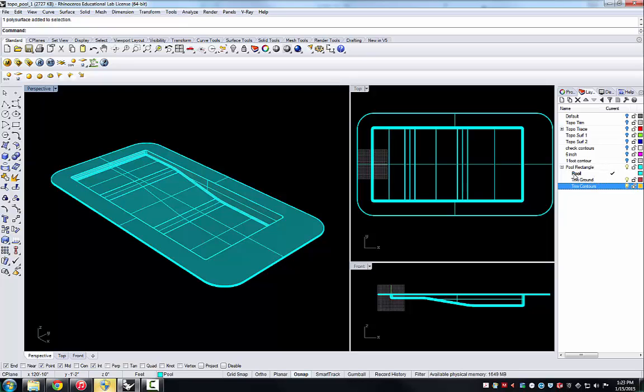And so if you go ahead and create a layer called Pool Rectangle, I've given it a turquoise color, and then a sublayer of Pool, turquoise color, and then 2 more sublayers, Trim Ground and Trim Contours. Then we have the collection of layers that will allow us to have this version of the pool adequately integrated into the site without actually losing data that we've had before. And we're going to be working in the pool layer itself, so that's the current layer.